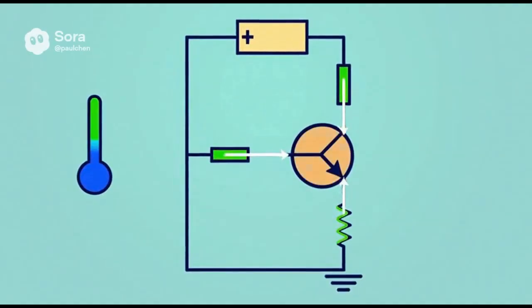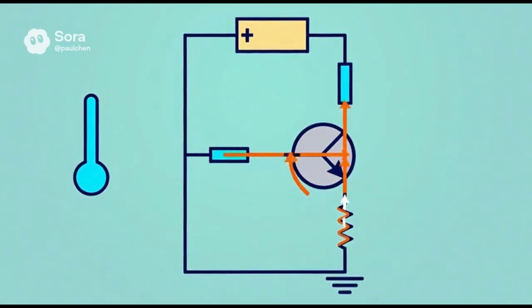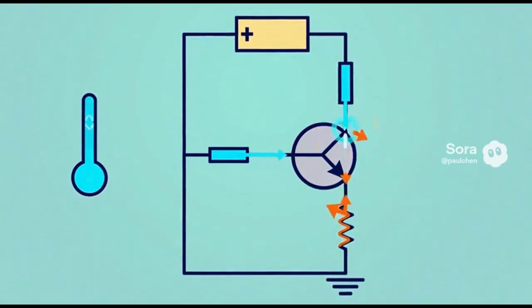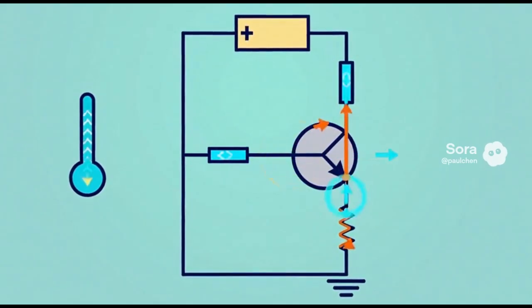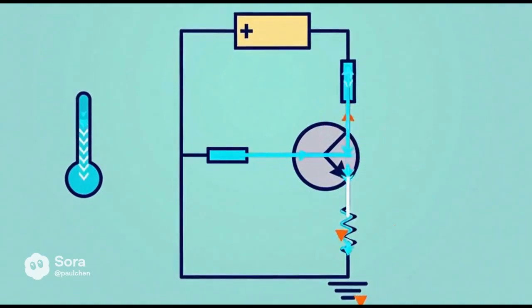The emitter resistor converts voltage into current. As the emitter voltage rises, current increases. If temperature or transistor gain changes, the resistor automatically pushes back. This negative feedback makes the bias stable and predictable.